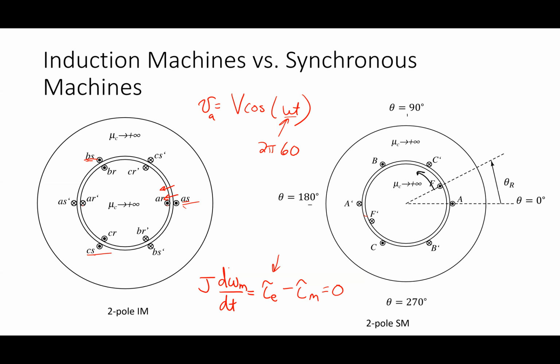All right. So basically, those are two ends of the spectrum. One end is at 0 speed. There's a 60 hertz current that ends up in the rotor. It gets yanked along to start producing torque. And then at full speed, there's no current in the rotor and no torque production. Where we operate is somewhere in between. So we're going to go through that all today. Questions about those basic principles? We do a lot of derivations, but those are the basic principles by which this thing operates.